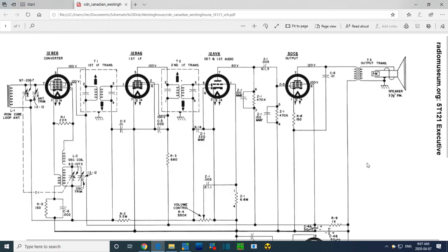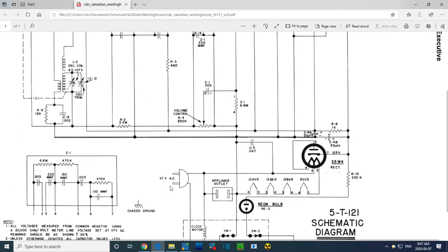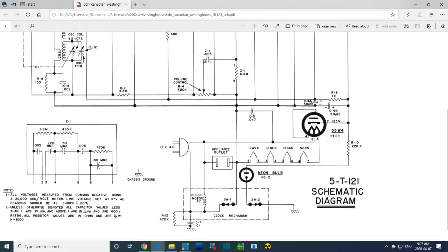Okay. Just listen to this though. That's the radio playing, and then I'm going to put my finger on the chassis. Putting my finger on the chassis, to me, increases the kinds of problems I'm picking up on. And that kind of goes to this idea of that bigger capacitor draining out the chassis. You'd be fooling around with which one? This one. This is the one I'm paralleling with a 0.1.